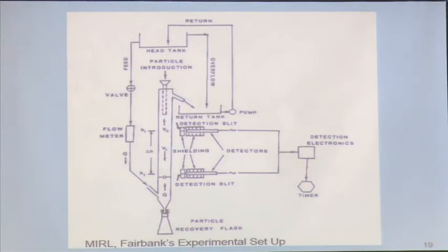I know that this is when it has basically reported here, and when it is just going out of this system, then again this another detection system is again detecting that particle. So if you have a timer, you know how much time it has taken, and you know the distance of that. So I can easily calculate the velocity of that particle, and you add to that the upward velocity of your water. So you get the settling velocity of that particle. Okay. So I thought that was very accurate, but still there will be error.